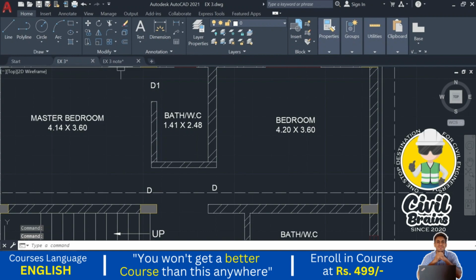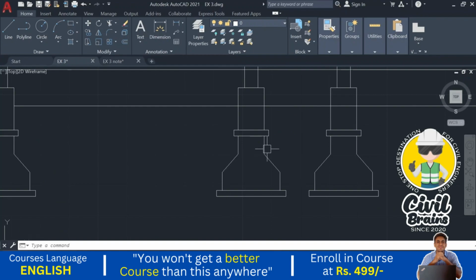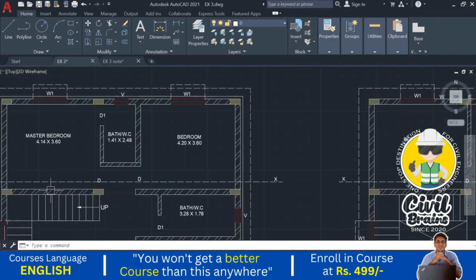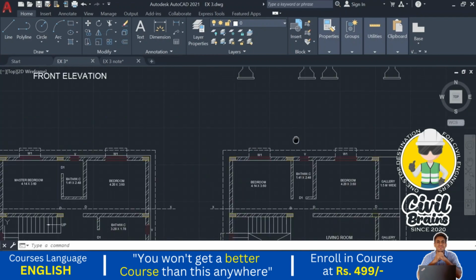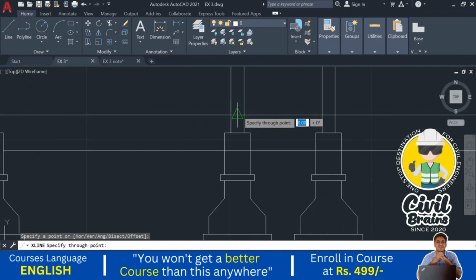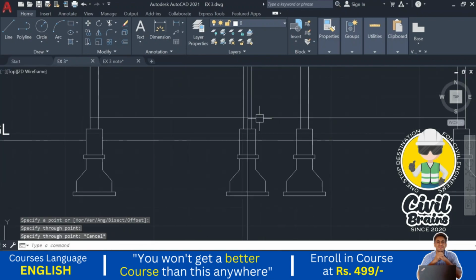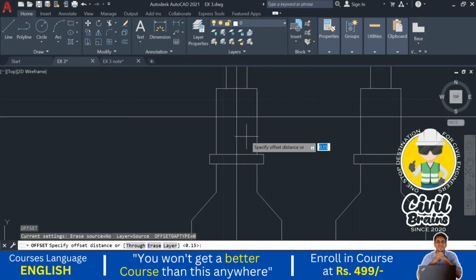So again we need to change here. So remaining things are same. If you see this one, this column, the size, dimensions, everything will be same. It is not changed, only the wall is changed. So again we have deleted the center line. I just draw the center line. So depth of the foundation we have taken as 0.15, that is totally 0.3, right?